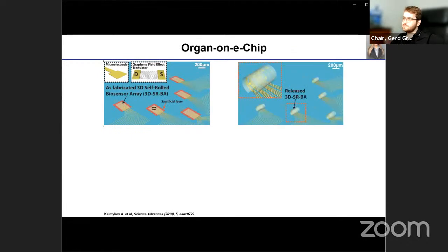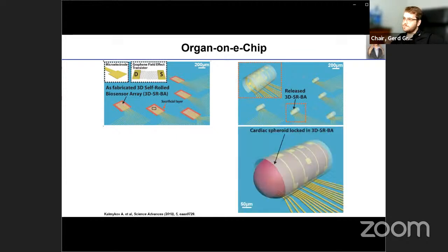We can assemble different types of sensors, such as active sensors, as field effect transistors based on graphene, or microelectrodes based on metallic electrodes coated with conductive polymers, such as PEDOT:PSS. The biggest advantage of our approach is that we shrink wrap sensors around the tissue and monitor the electrophysiology of the tissue from all sides of the circumference of this tissue, essentially.